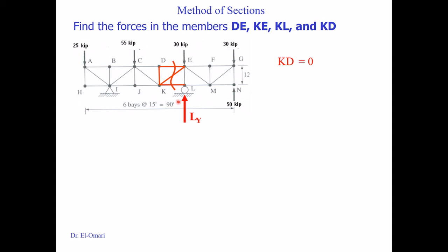Please, this is an important note and a mistake that always happens. Some would just take the cut without solving that, and then when they draw this, they get stuck because they will have too many unknowns. Notice that when you take the cut, you have to see now the reactions of these members. So always find it. If the question asked to find these three members, then you could have cut there and found them without the need to find any support reaction, working on that right hand side. But so we need to cut there.